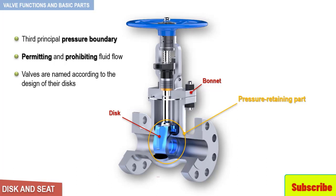The seat that you can see here provides the seating surface for the disc. In some designs, the body is machined to serve as the seating surface, and seal rings are not used. This is the case of our example here. However, in other designs, seal rings are threaded or welded to the body to provide the seating surface.